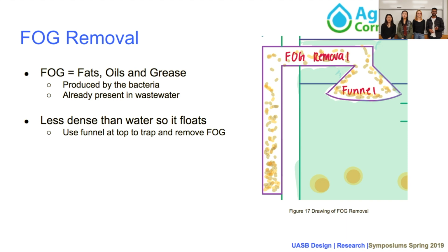after every tip of a bucket, when the water level rises, it will remove all of the fat, oil, and grease which are lying at the top of the water, as it is less dense than the wastewater and water we are treating. This was not taken into account in our previous reactor, and we realized it's something we have to take into account in our new design. At the bottom of the funnel, there's going to be a deflecting panel, which ensures that none of the methane gas bubbles created within the reactor enter this funnel and stop it from being able to remove the fats, oils, and grease.